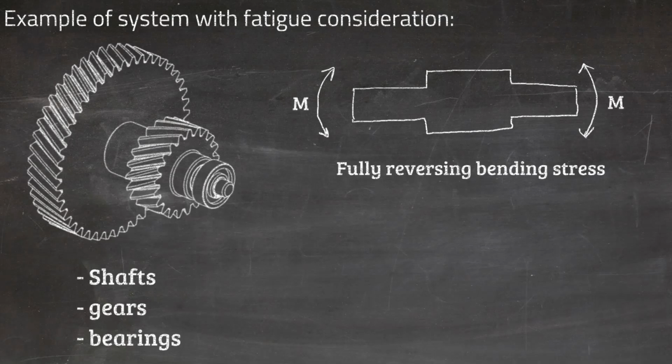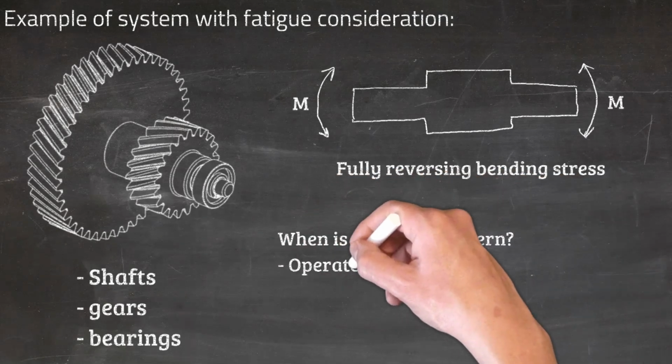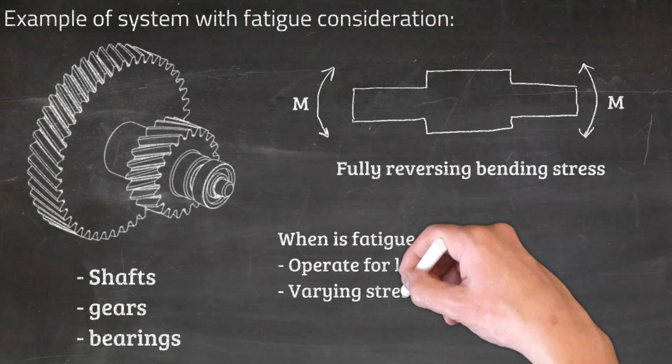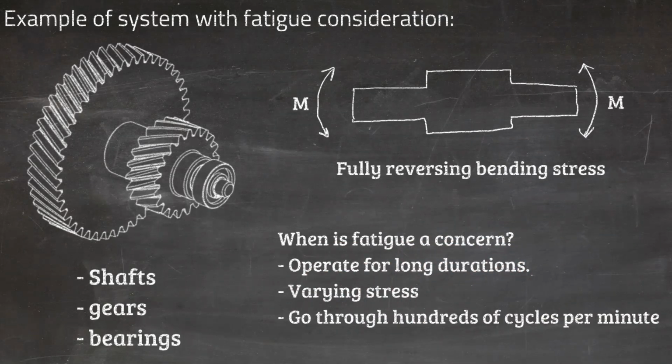So the design engineer must take fatigue into consideration. Generally, we can say fatigue must be considered if a component operates for a long duration and undergoes varying stress. Typically, such systems will go through hundreds of cycles per minute.